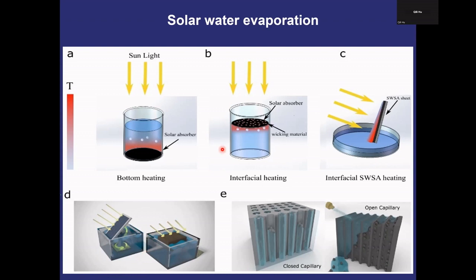So this is a very active research area today. You see all this exciting work coming in this direction. What was the technology then? Usually people put a foam-like material on top of the water, and this material wicks the water slightly up, and then they put some nanoparticles to absorb the light. Well, there's a problem. Number one, this foam-like material easily gets clogged. When you evaporate, the water has impurities, you have salt, so you easily clog it afterwards.